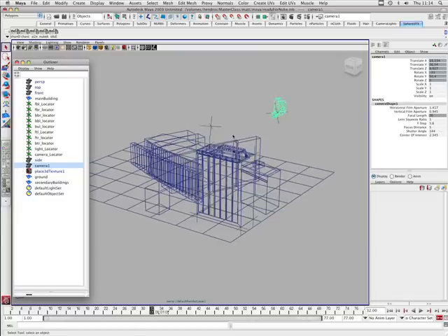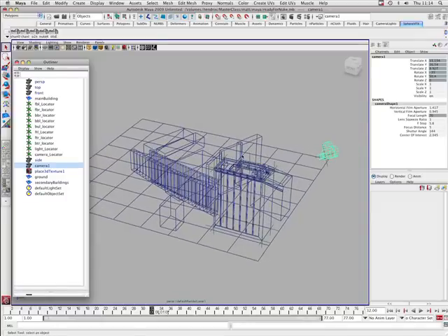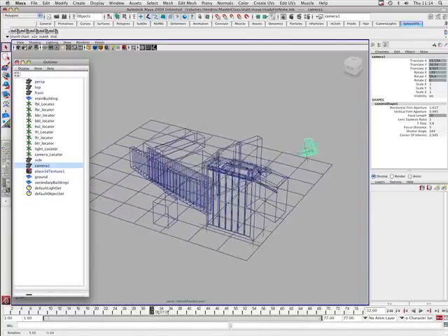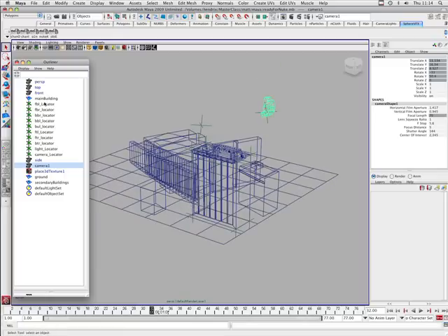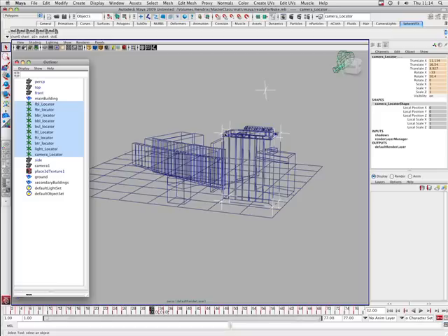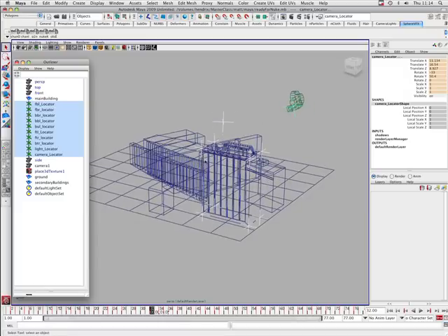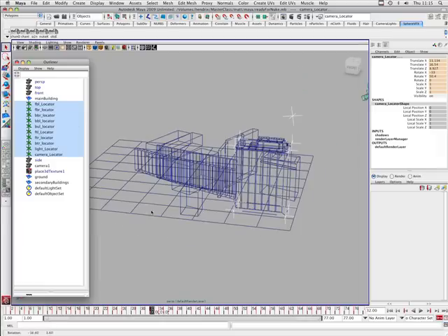And I don't want to go too far into Maya, because we're obviously interested in Nuke. But all this geometry was based on the camera position and building really from eye where everything was in the scene. So that was then all exported as an Autodesk FBX file. And these locators that you're seeing here are just nulls. I put them in because I wanted to make sure I knew exactly where this building was on all the corners, in case Nuke had any problem reading or positioning the information from the FBX. As it happened, it came in absolutely perfectly first time, so I didn't need those at all.